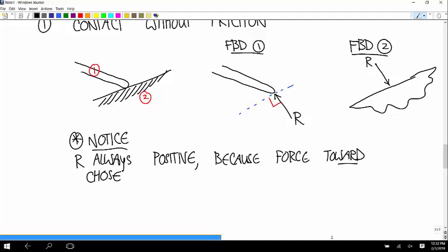So we know that direction. So if you ever do a problem like this and you draw your R like that and then you go through the calculations and you get an R value that's negative, you know something went wrong, because an R value that's negative would say that the ground is pulling on that object and a frictionless contact can't pull. So either the thing is designed wrong or you made a calculation error.